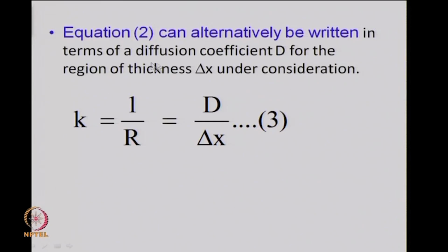It is a different matter that this theory may not be in general agreement with experiment across all ranges of parameters, and you recall, especially the people who have had the second year undergraduate course with me, that it is this particular dependence, K proportional to D, that is the basis of the variety of models that were required, because in practice you do not find the proportionality of mass transfer coefficient to the diffusivity to the power 1.